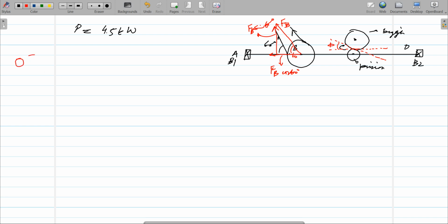When the gears are sideways like this, the line will be like this, and the pressure angle will be like this. So remember, there could be two configurations: one in which one gear is on the lower or upper side, and the second is a side by side gear configuration. This is called WN, as we have seen.